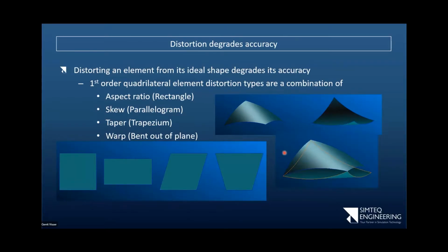To prove that, I just drew them both, and these lines in kind of brown are the bottom one's edges, and you can see it comes to exactly the same corners. So in other words, exactly the same node movement gets me two different possible shapes. In reality, what the finite element method will do is it'll actually combine these two shapes.